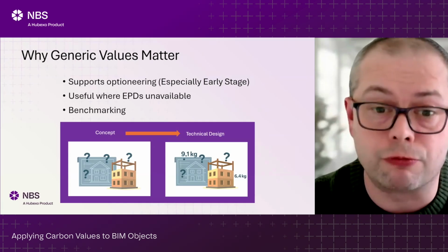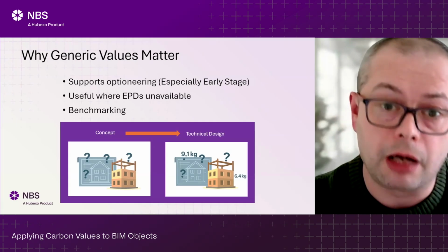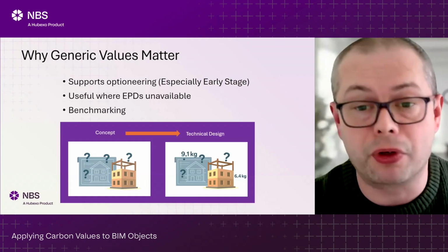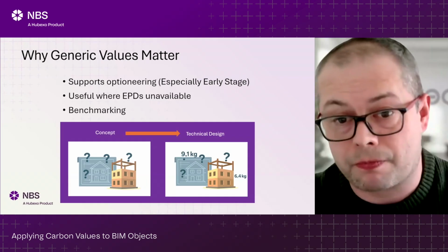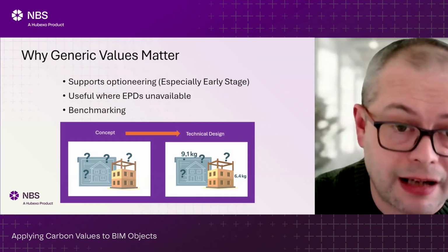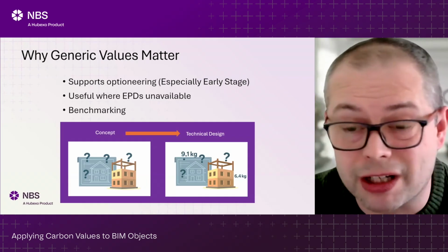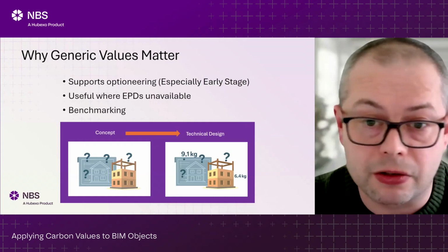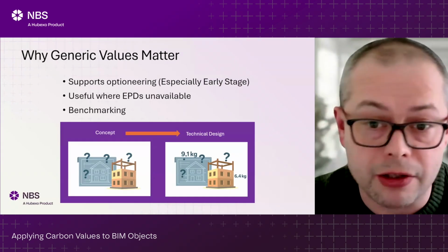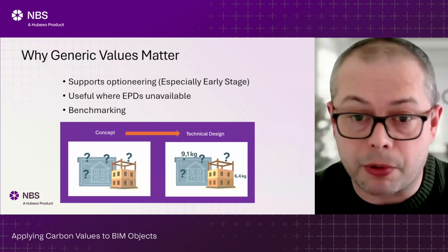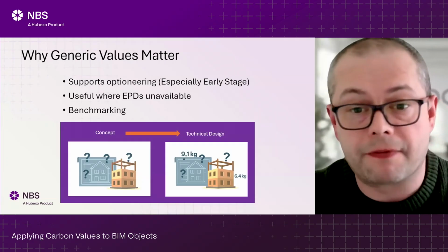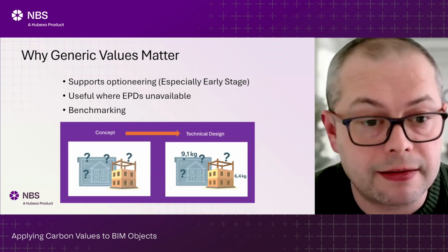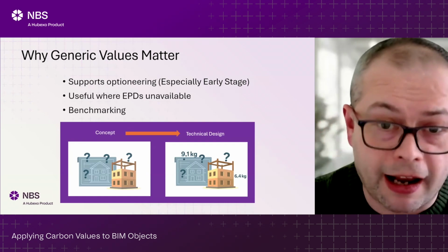So this is where generic data really, really comes into its own. You can provide those calculations and you can benchmark what that should be at that point. But also, as that project progresses in terms of the technical design stage, it's really useful where EPDs aren't available. So if you are getting to technical design, stage 4, and you know all of the different manufacturer products that you want to specify, if some don't have EPDs available, you can plug those holes with generic data. So it has a place.